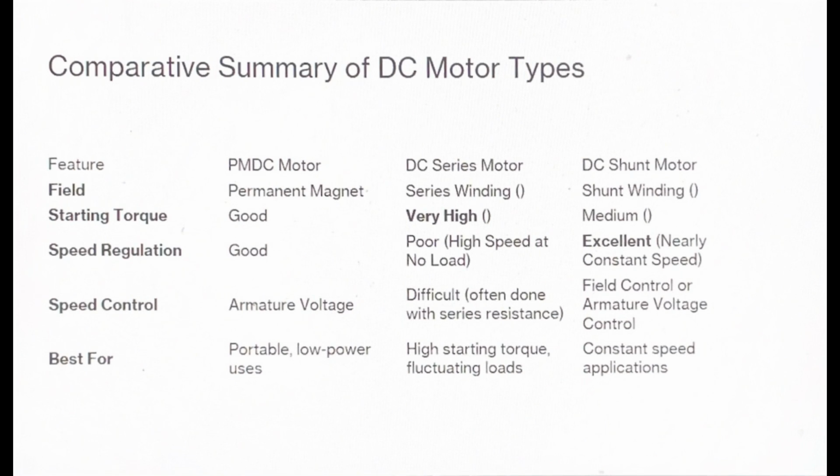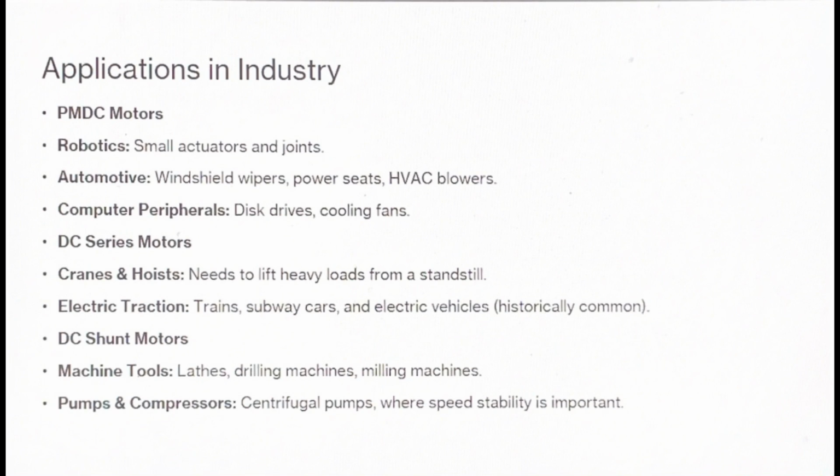And the best use for PMDC is low power uses and portable, low weight applications. For series, high starting torque and fluctuating loads. Shunt, constant speed applications. And for the last slide, applications in industry.